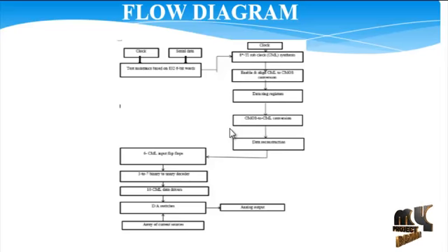The use of a shift register as a core memory block in the test assisting structures is present in the work. Higher measured SFDR performance up to 800 MHz among the published 6-bit CMOS DACs. Scalable test assistance block: detailed description of an on-chip test assistance apparatus. A high-speed CML Mux implementation for data reconstruction, and a high-speed CML gate design approach based on only 2 gate types.